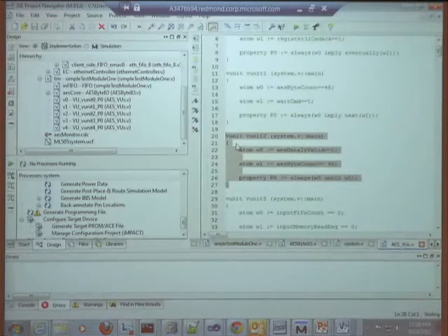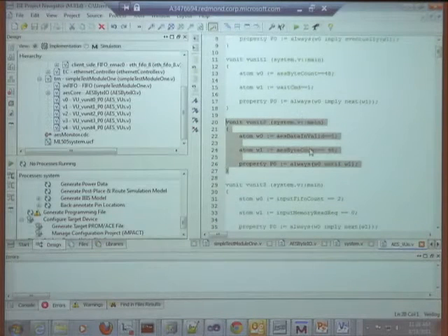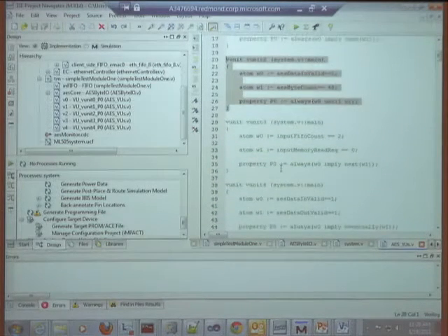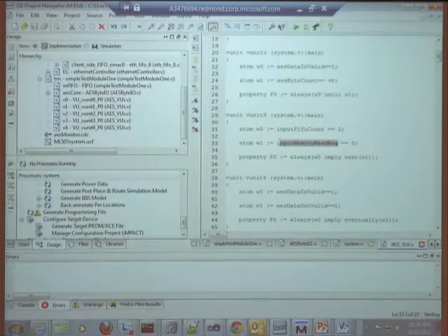So in the next assertion, there is no notion of time. Again, we have another next assertion which says if the FIFO is full, the next thing that should happen is that you stop requesting things. These are more like transaction level assertions.